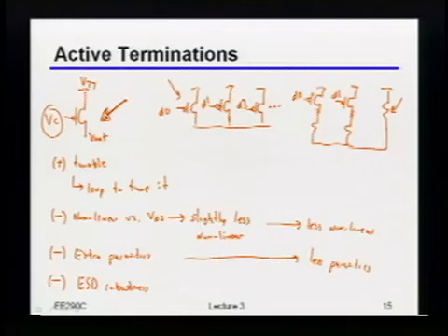Okay? And I think that's basically it. Maybe it actually has slightly more ESD robustness just because you have resistors in series with everything rather than gates directly on the output node. But that's not a huge effect. As I said before, you still need to worry about the ESD protection. Okay?